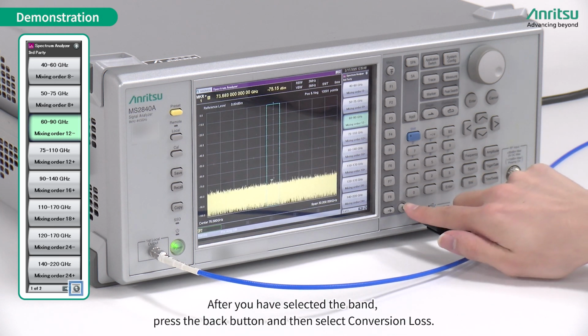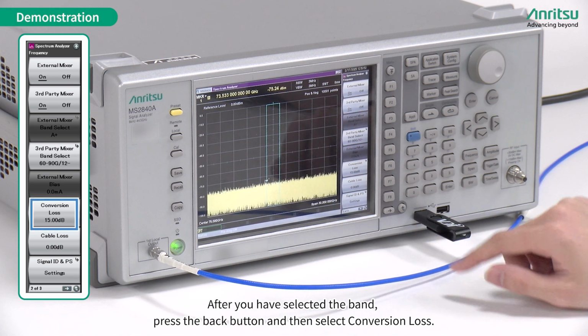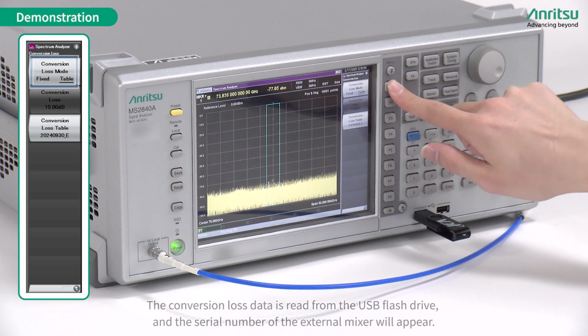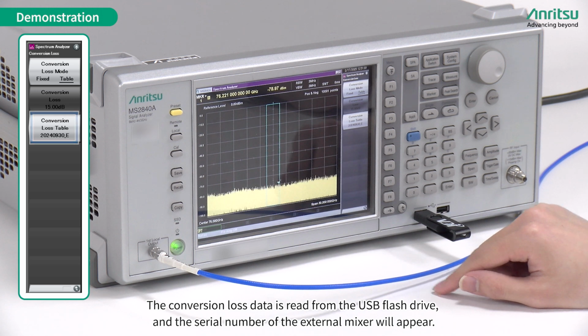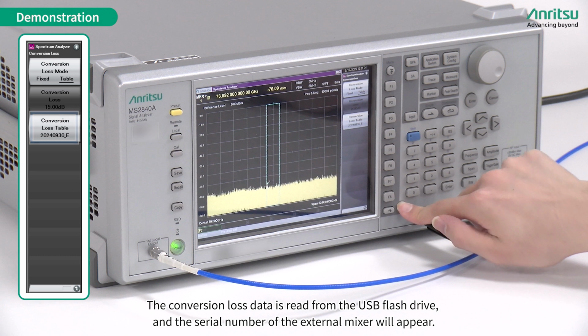After you have selected the band, press the back button and then select conversion loss. Change the conversion loss mode to table and then select the bottom button. The conversion loss data is read from the USB flash drive, and the serial number of the external mixer will appear.